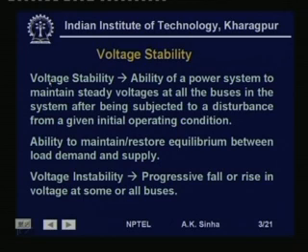What we really understand by voltage stability is that it is the ability of a power system to maintain steady voltages at all the buses in the system after being subjected to a disturbance from a given initial operating condition.